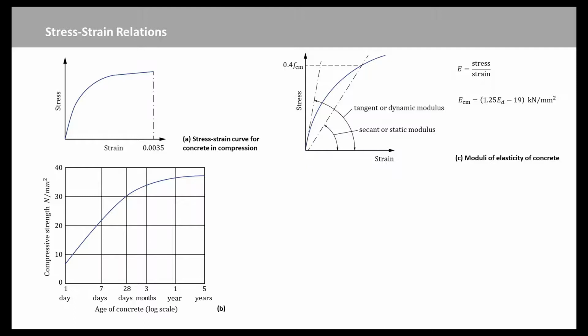The dynamic modulus of elasticity, Ed, is sometimes referred to since this is much easier to measure in the laboratory, and there is a very well-defined relationship between Ecm and Ed. The standard test is based on determining the resonant frequency of a prism specimen. It is also possible to obtain a good estimate of Ed from ultrasonic measuring techniques.